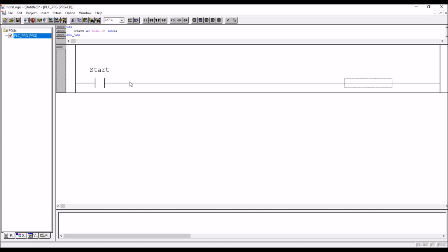So now when you press start button, what immediate programming is required? See, S1 start button and stop button, both are push buttons. Okay, so those signals data will be erased or will be lost as soon as you release the start button. Okay, so what you have to do? First you have to store that start signal in some location, memory location. Okay, so to do that, I'll take one memory bit